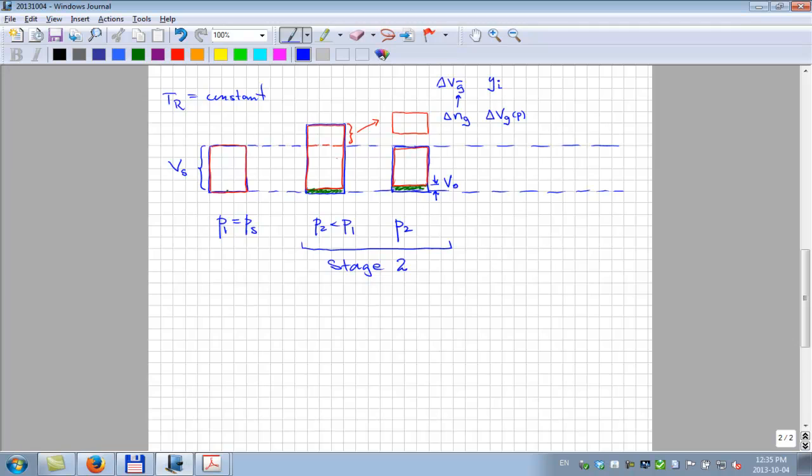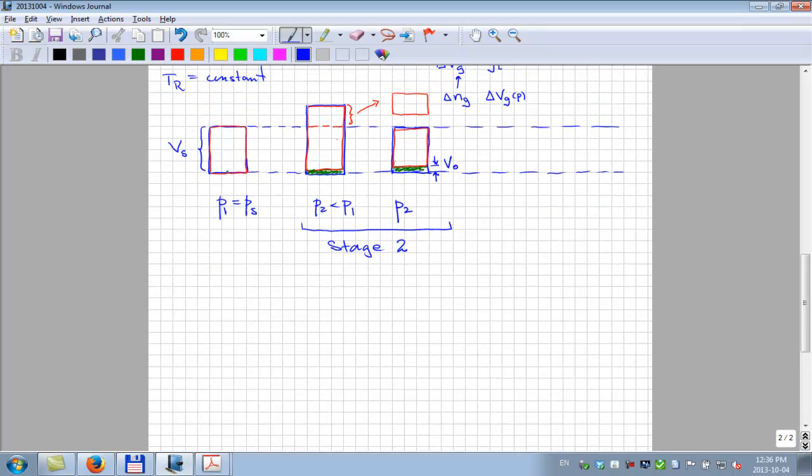Basically, the differential liberation test has typically somewhere between 6 and 10 stages. In the constant volume depletion test, because it's a little more expensive test, you're measuring the composition each time. Typically 6 stages on average, 6 of these stages, the last one being standard pressure. So usually of 6, you might in some cases have 8.